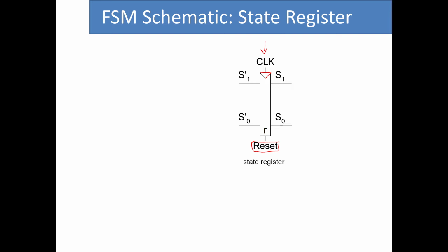And what happens when you use this reset is that you basically put your system into state 0. And if you remember, state 0 was when LA was green, LB was red, and for the state encoding it was represented as 0, 0. So whenever you reset this system, S1 and S0 both become 0. And it doesn't matter whether you use synchronous or asynchronous resettable D flip-flops, right? In the grand scheme of things, those two both behave the same way. Of course, if you use asynchronous, that means that when you provide this reset signal, instantly the output goes to state 0.